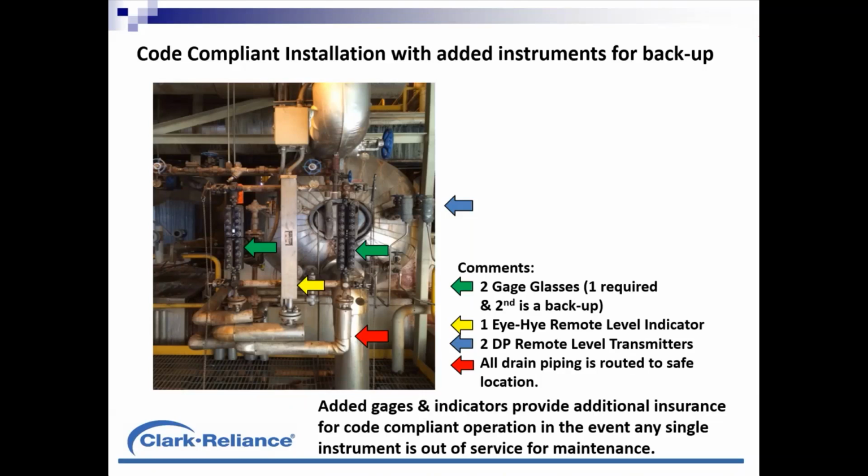The last thing, I've got it coming up on another slide as well, but if you notice that small diameter tubing going off of those differential pressure transmitters, these devices do require periodic maintenance. It's encouraging to those in attendance to check that piping periodically, make sure it can be blown down, flushed, so that you don't have any sediment buildup in those sensing lines.